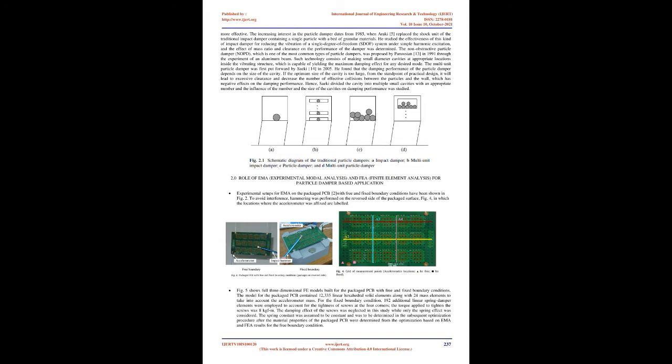The multi-unit impact damper is the descendant of impact dampers. In 1969, Masri [12] obtained the exact solution for the steady-state motion of a multiple-unit impact damper attached to a sinusoidally excited primary system, verified by numerical simulation and experiments. He found that, compared to the impact damper of equivalent total mass, as to reducing vibration, especially reducing the noise generated during the damper's impact process, properly designed multi-unit impact dampers are more effective.